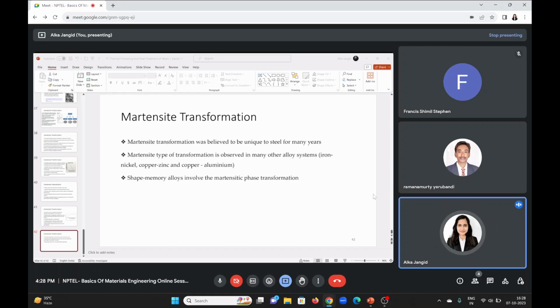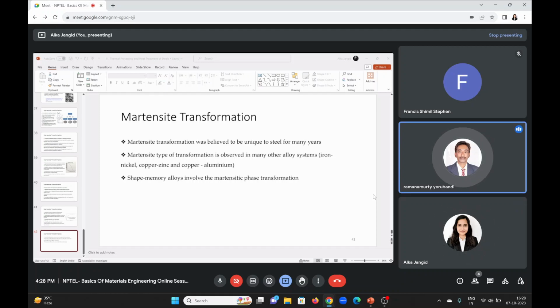Like in the case of tool steels, you require a very high percentage of carbon because you want to form carbides, such as tungsten carbide or molybdenum carbide. These help with cutting properties and hardness. So it depends on what properties you require, in tool steels and die steels. Okay, yes, thank you.